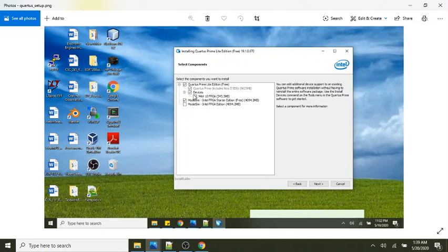In this case, I installed a device, the MAX 10 FPGA, and then it's also got the ModelSim Starter Edition. So this is everything. You don't need this last one checked. You just want the Starter Edition for the ModelSim. So just make sure that you see all of these check marked here when you first run the install, when you double click on that executable file.